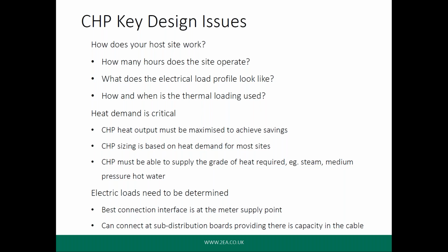There can be a temptation to fit the biggest combined heat and power unit into the site based upon the peak electrical demand, but that would be wrong. It is a careful balancing act that needs thoughtful modelling and a deep understanding of the site's operational energy profile to ensure the best fit. Again, more later. Finally, for this slide, we mustn't forget the electrical side of things. Whilst the electrical connection is often less complicated than the water connection, and many trades refer to this as running a piece of wet string, it can sometimes be challenging to find routes for cables which grow in size and cost the longer the run required.